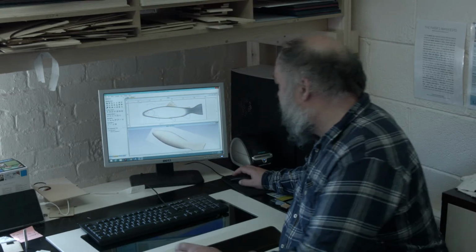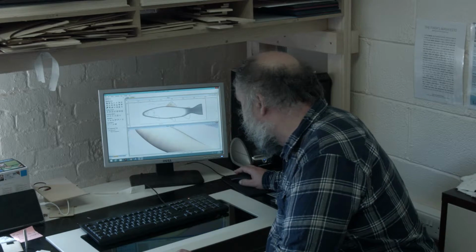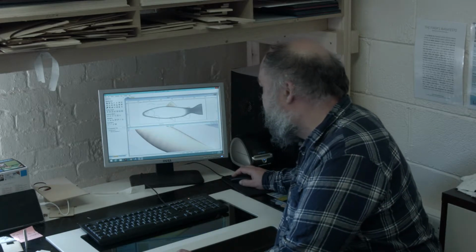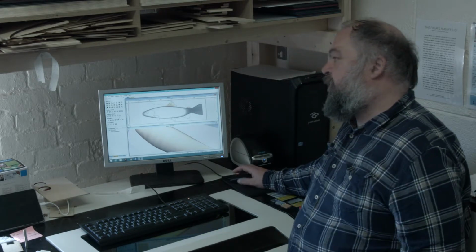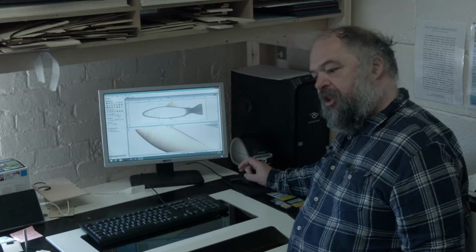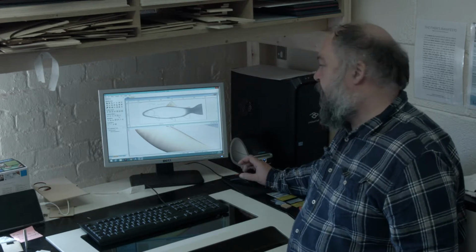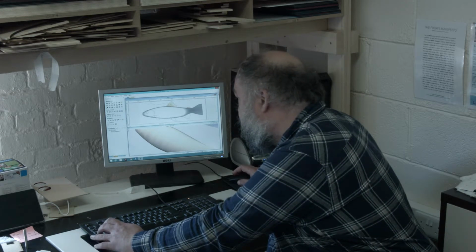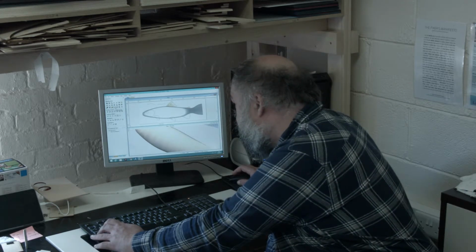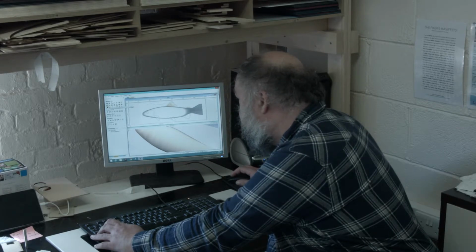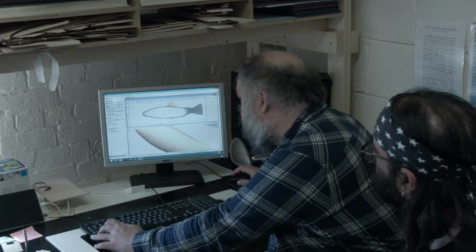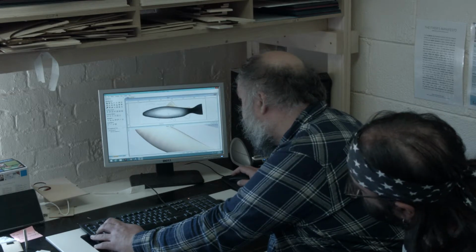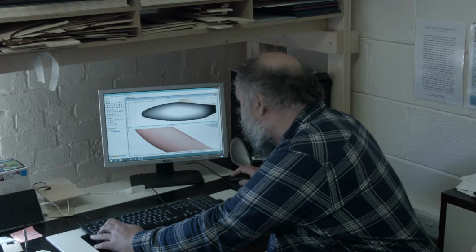What you can now do is we can use this shape, which is the actual outline of the fish, to actually trim that shape. So it'll then shape it into like a cookie cutter. Basically cookie cutter, yes. Which is clear outside selected component outside of vectors. So I've got to select that and then the shape.